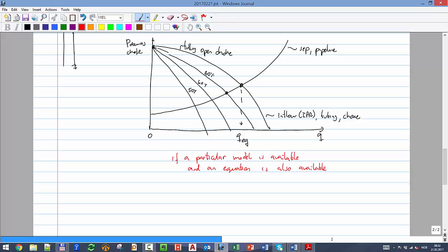And the equations usually, just to give you some idea, for an ESP, for a pump, look something like this. Delta P equals a coefficient A, which is a function of the frequency, times Q squared, plus B, where Q is the actual rate, plus C as a function of the frequency. And for a choke, something like that: a coefficient, let's call it D, times Q squared actual.